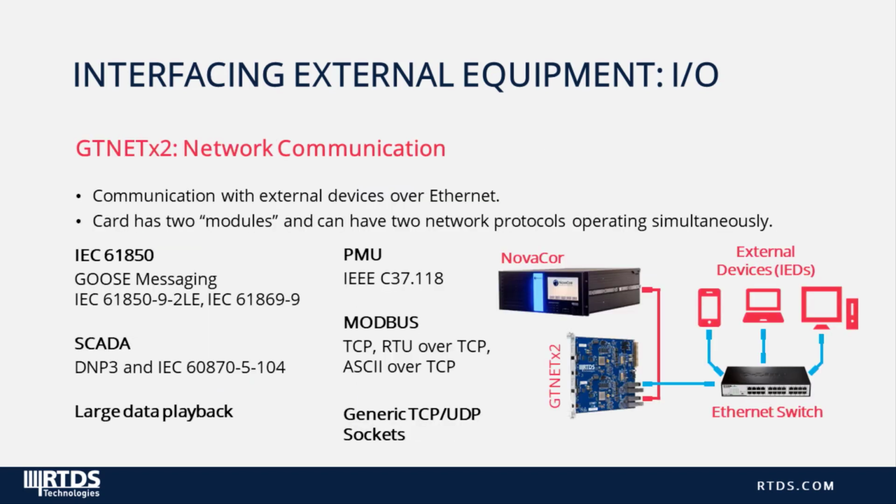We also have communication protocol-based I/O, which is commonly used in distribution automation, whether that is using the Modbus protocol for power set points from a PPC to a simulated generator, IEC 61850 for protection testing, or the SCADA protocols or generic socket integration for DERMS system testing. We won't be using these for testing the IntelliRupter today, as it relies on traditional analog and digital I/O.